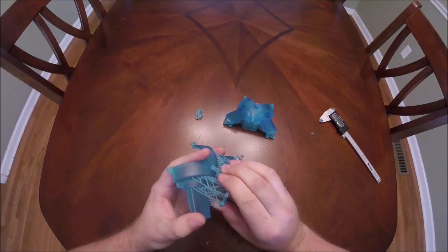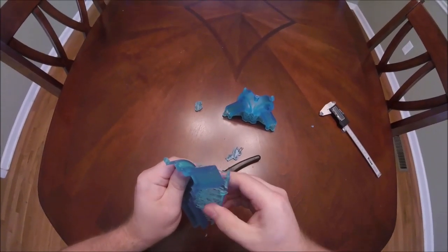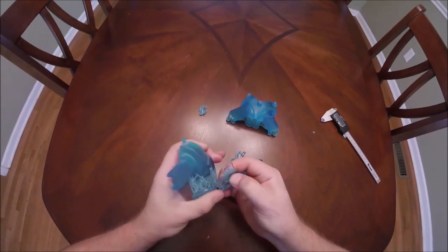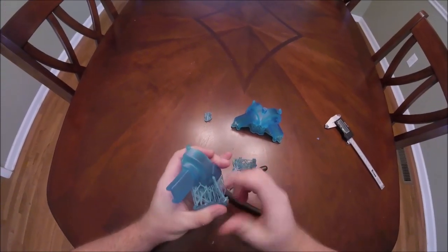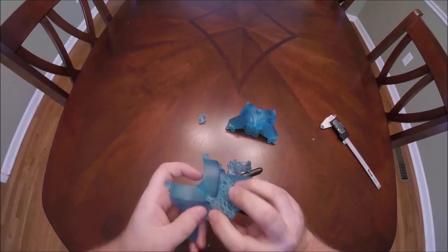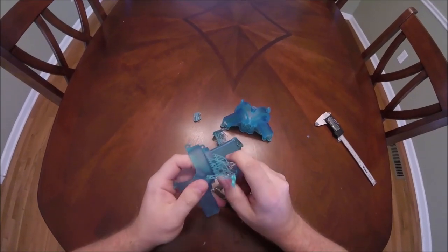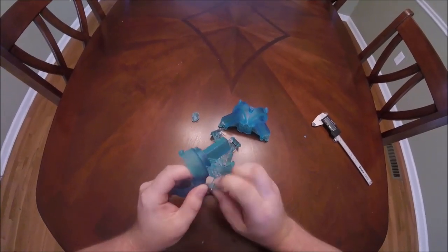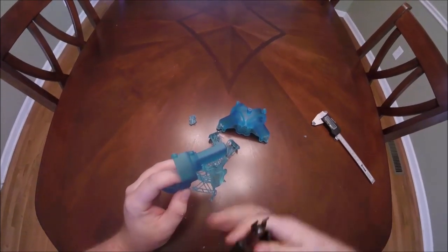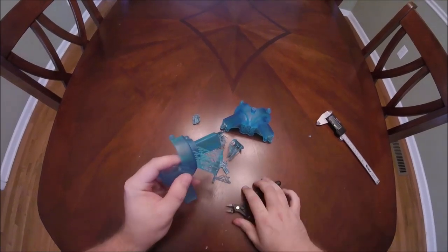And it's all looking really good so far. Remember, I'm trying not to scratch the part with supports, so I'm kind of pulling away from the part as I remove the support structures. And you can see there's very little support artifact left there. I'm just going to keep removing these little sections until I've got this part completely clear of support structures. Sometimes you get little areas like this that are kind of difficult to get off, and I might just come in here with some clippers and clip, get that out of the way.